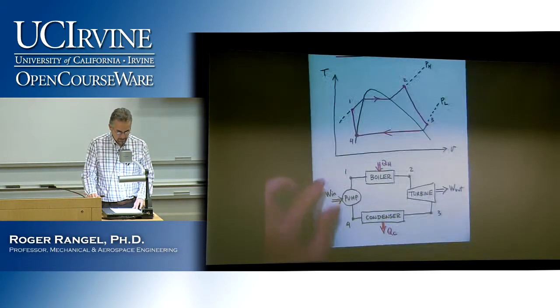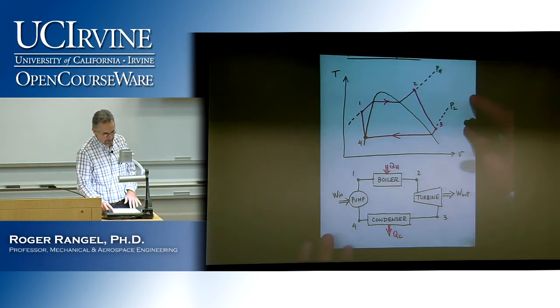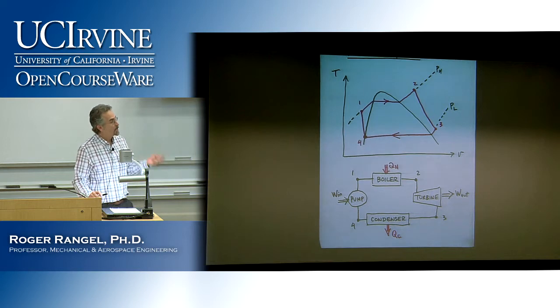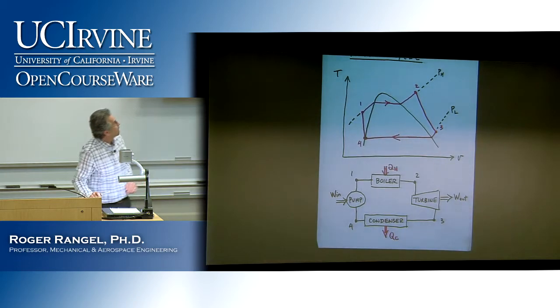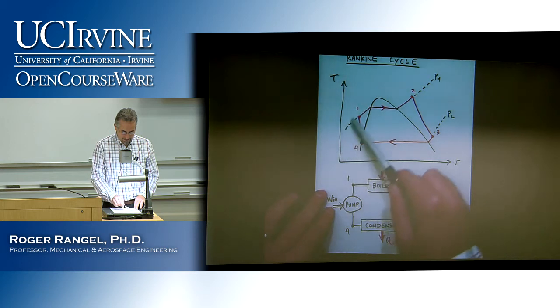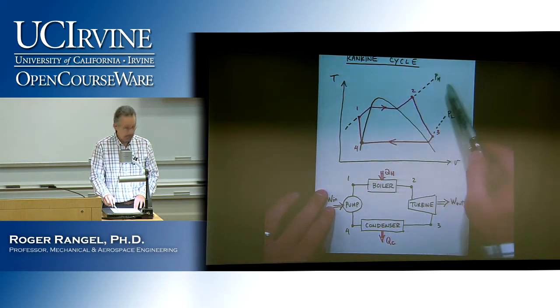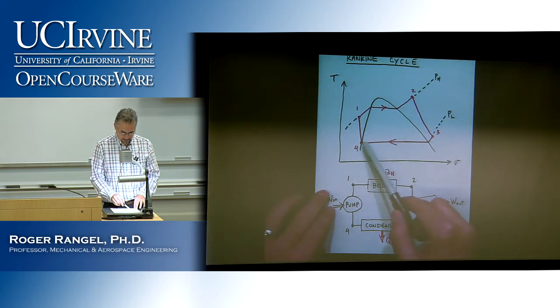Here's a Rankine cycle. So this one is, as I told you earlier, the one you would see in a power plant. It's also 2 isobars and 2 adiabatics. So you can see the isobars here. I only did the TV diagram because I'm going across the dome. Right? So here's my isobar coming up, then going across, and then going up, the one at the high pressure. And here's the one at the low pressure, down here and then across.